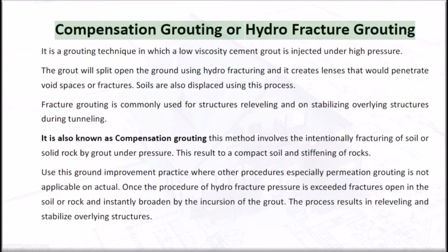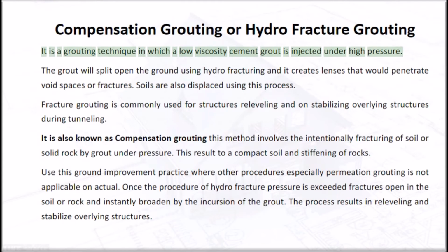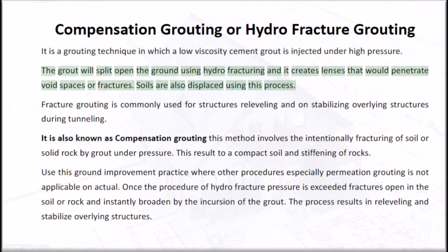Compensation grouting or hydrofracture grouting. It is a grouting technique in which a low viscosity cement grout is injected under high pressure. The grout will split open the ground using hydrofracturing, and it creates lenses that would penetrate void spaces or fractures. Soils are also displaced using this process.